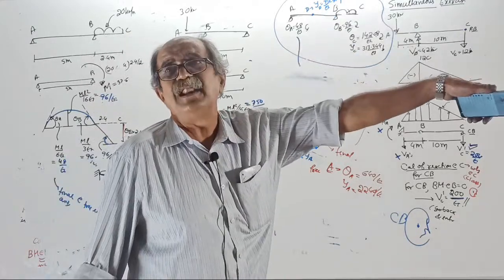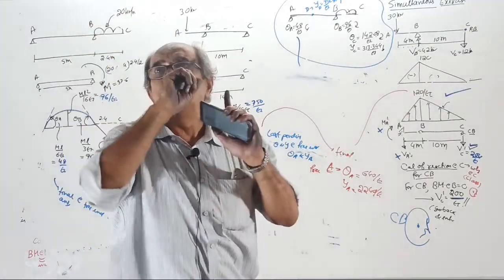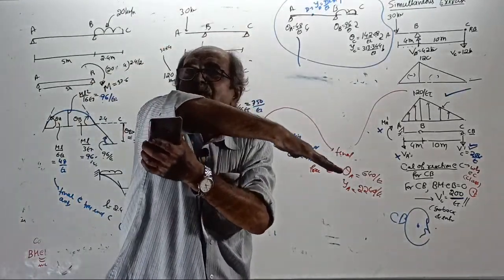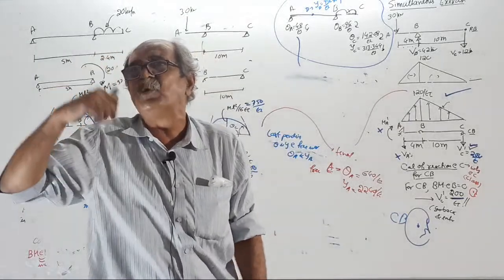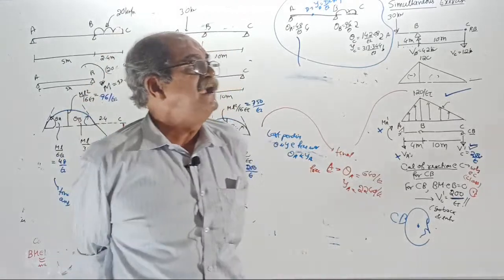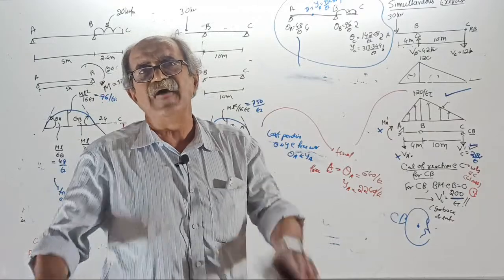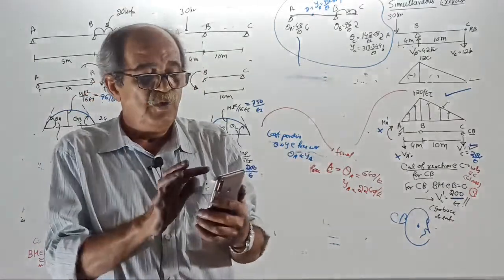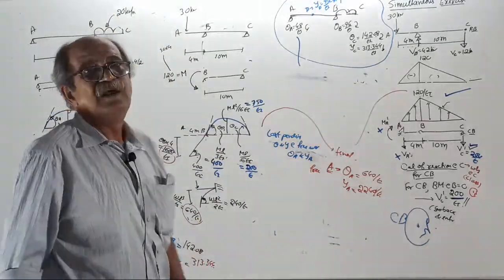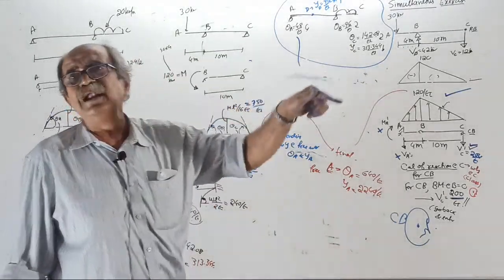Suppose there is deflection there. Then whatever slope you got at the overhanging support, multiply by the overhang. That will give the shift of the overhang. Multiply the slope at the overhanging support with the overhang. Then add deflection for the cantilever. Point load, WL cube by 3EI; UDL, WL power 4 by 8EI. That's all the trick. So it requires just half a minute to find any one of that. If they want the support, not half a minute, a quarter minute. If they want the free end, half a minute.